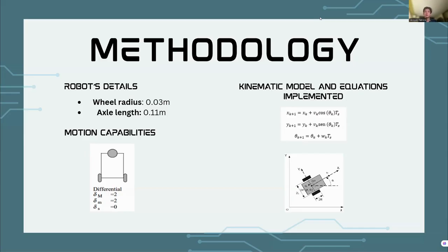Using the standard equations, we relate the linear and angular velocity of the robot to the angular speeds of each wheel. After that, we implement the kinematic equations directly in MATLAB. The code was organized into blocks. We first configure the motors and reset the encoders, and then we calculate the wheel speeds required for each commanded motion. Finally, we defined the desired trajectory.